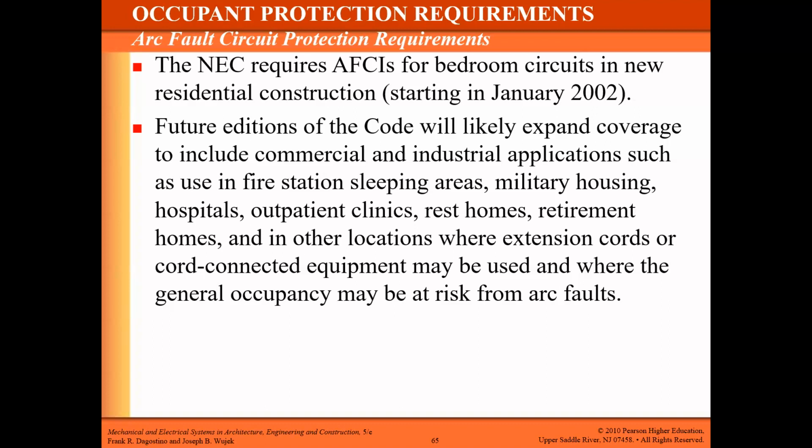So if an arc fault is detected, that circuit will also shut off. But these are required in all bedroom circuits in new residential construction, and I suspect that is just going to continue to expand just like the GFCI requirements.